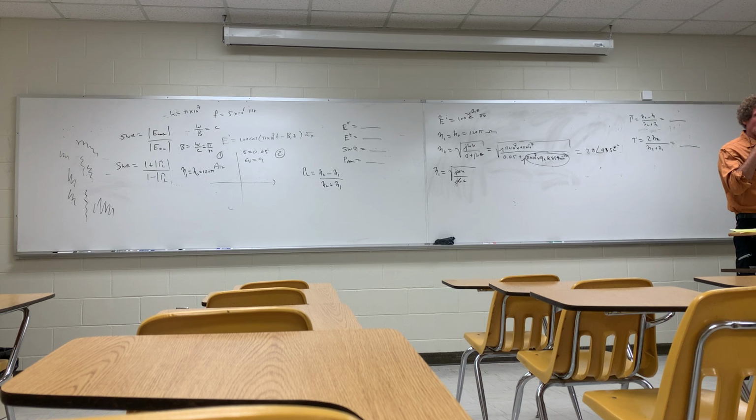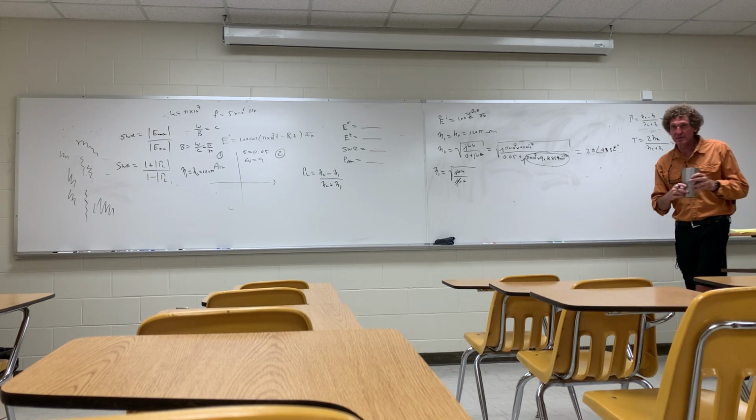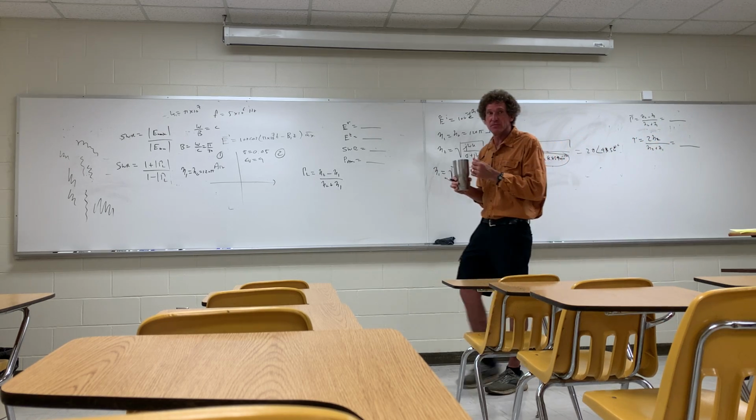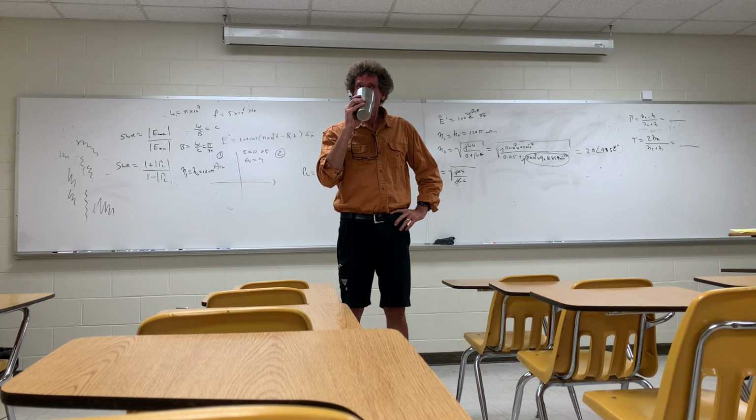I encourage you to bring your calculators, because there's a lot of stupid mistakes made with calculators. I found this out. Do we need to include the imaginary, the angle? Has to be complex, absolutely. If you don't do it with complex numbers, you're gonna get wrong answers, big time wrong answers, because that's at an angle of 45 degrees. It's not even close to being strict real.